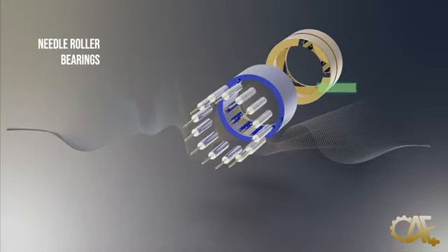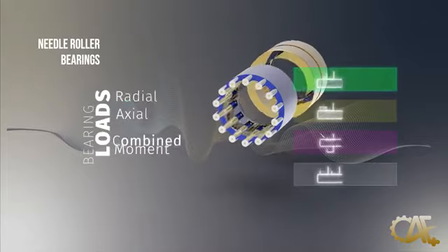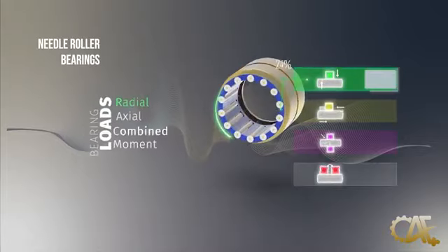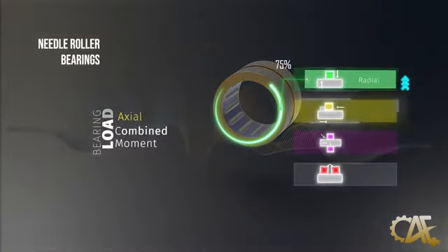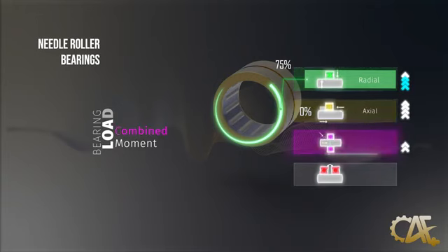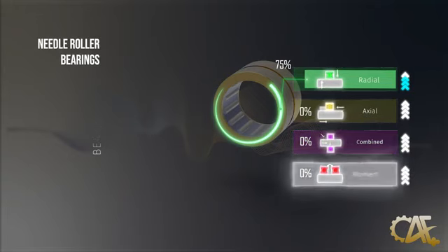An analysis of their bearing load performance reveals excellent capabilities in managing radial loads. However, they are less suited for applications that are subjected to axial and combined loads. Regarding moment loads, substantial moments can cause uneven stress distribution within the bearing, potentially leading to premature failure.